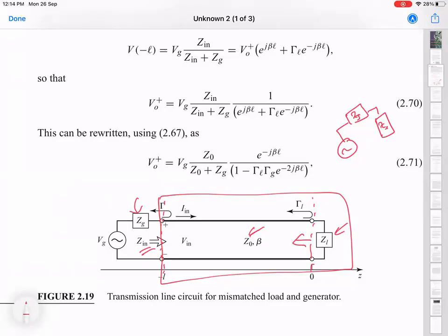Now, this is of course the most ideal case, a lossless transmission line perfectly matched to the source impedance. You know that there will be no reflections here, so you will set up only the forward-going wave, and that will just propagate and arrive at this end. The only change it experiences is an overall phase shift, which depends on the speed of propagation of microwaves in this transmission line.